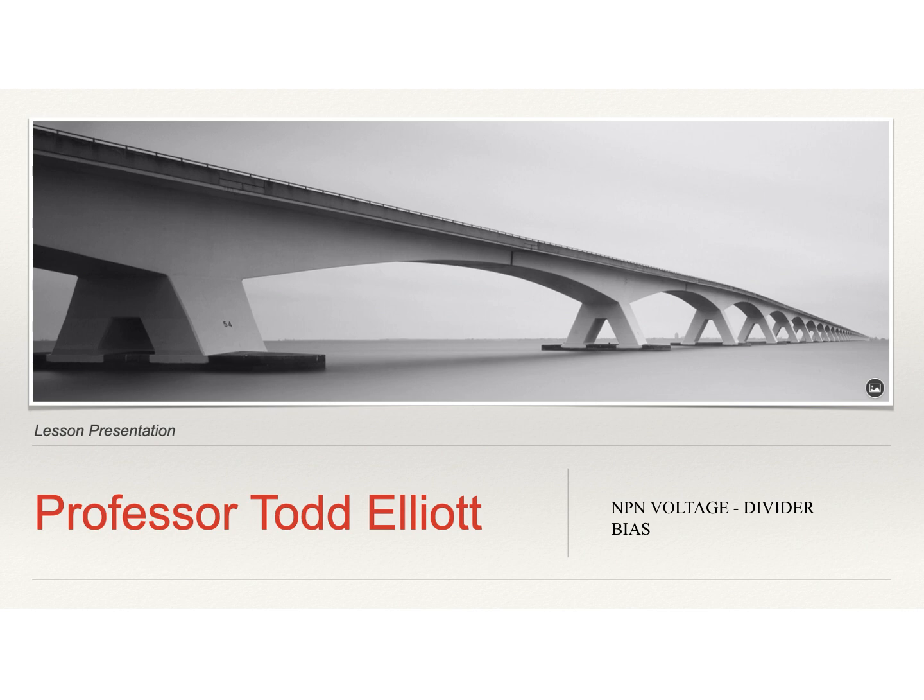One of the key advantages of using the voltage divider, now we're only looking in this video at the NPN voltage divider, but of course there's the PNP. The PNP transistors more or less work with negative supply voltages, but that isn't always 100% the case either, because you can use NPN transistors with negative supply voltages, just bias it in the right way. For right now, we're just going to stick with the shortcut method.